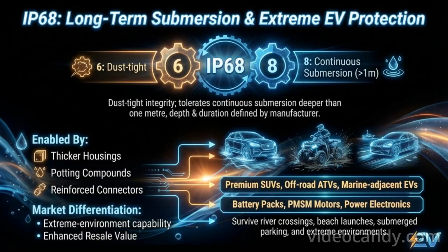IP68 is the premium deep-dive rating for EVs. IP68 keeps devices fully dustproof while allowing continuous water submersion, with the exact depth and time set by the manufacturer. Premium SUVs, off-road vehicles, and marine-friendly EVs use this for batteries, motors, and power electronics to handle river crossings, beach launches, or submerged parking. Thicker housings, potting, and stronger connectors add cost, but provide reliability in extreme conditions and improve resale value.